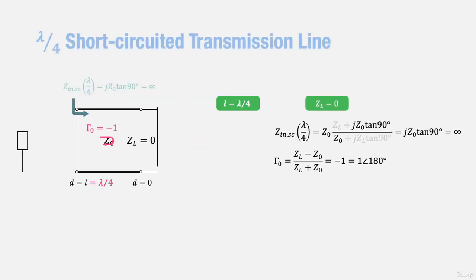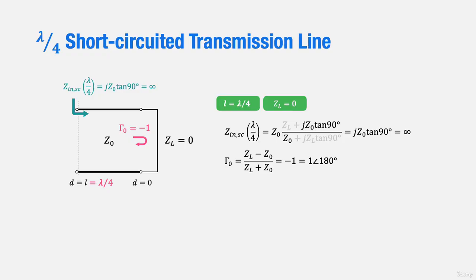Let's revisit the shorted and open lines we mentioned earlier. We discovered that for a quarter-wave shorted line, the value of tangent beta d equals tangent 90 degrees, which tends to infinity. What does this imply? Well, folks, do know that a shorted line is not always a short circuit. That's right. When we connect ground to a quarter-wave line, a short circuit will be converted into an open circuit.